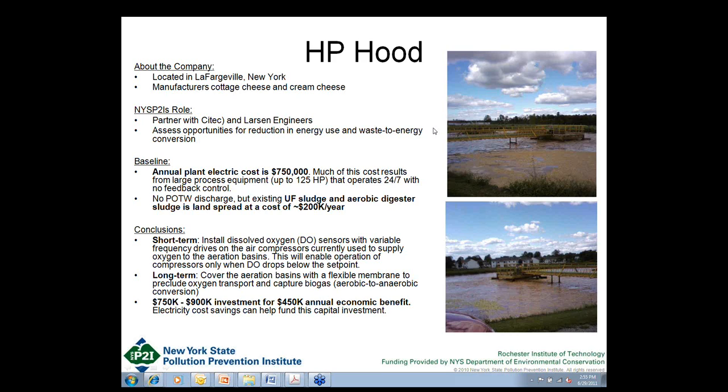It's very reasonable, and before we do the full conversion, we're actually just starting with some short-term improvements by putting in variable speed drives, et cetera, so that they don't have to be operating 100% and using energy 100% of the time. There are opportunities to shut them down intermittently.